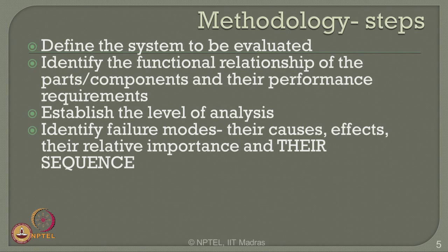It is because of this reason I told you in the beginning that it is essential. First, we have got to make a scaled working model of the system for which we need to do an FMEA study. So, from the experimental investigations of a scaled model of the system, let us subsequently identify different failure modes, their causes if the failure materializes, and their consequences, or what we call effects of this failure on the overall performance of the entire system.